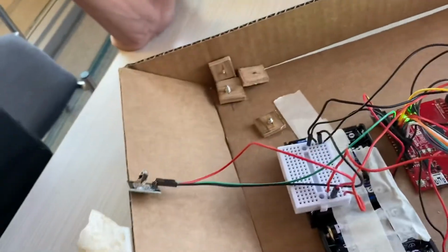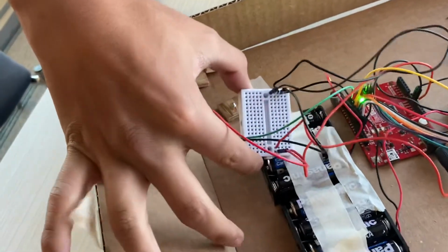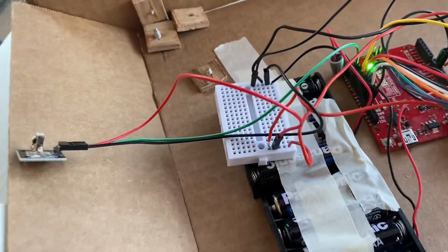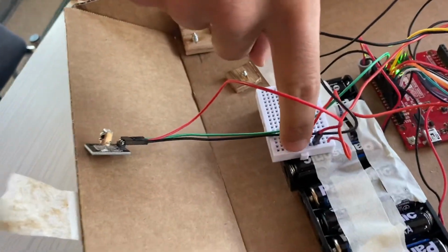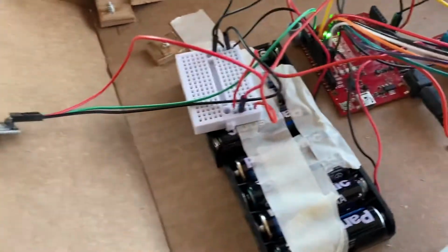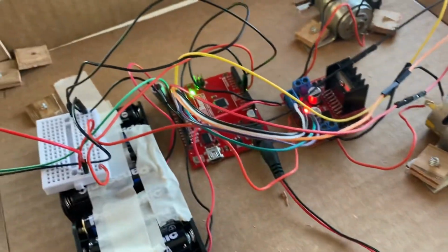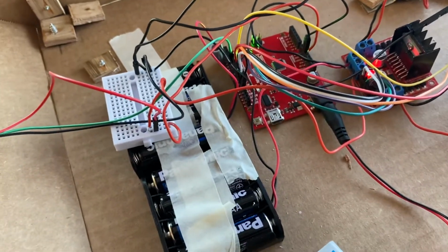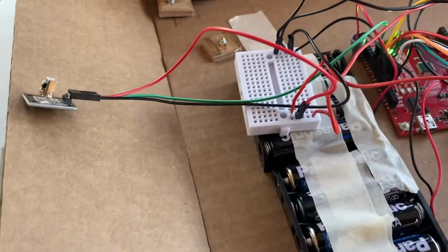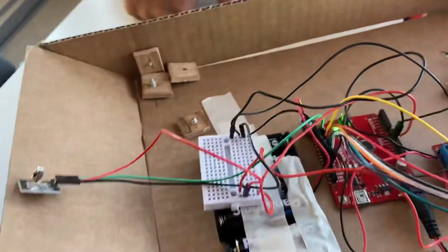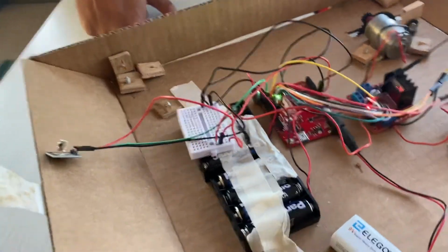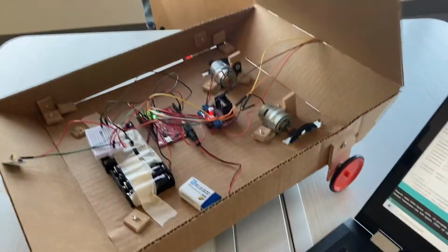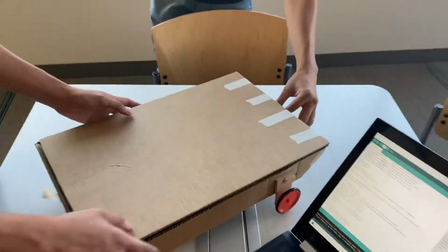And we have the breadboard here just because it makes everything more organized. We have all our ground wires connected. Ground wires, yep, to one line. And then these are all powered by a 5-volt charge coming from this. Yeah, because the batteries are connected to the motor board, the L298, right? Yep. And then from there, we're taking the 5-volt power source, going to the breadboard there to power the receiver and breadboard. So basically, that's pretty much it for our electrical construction.